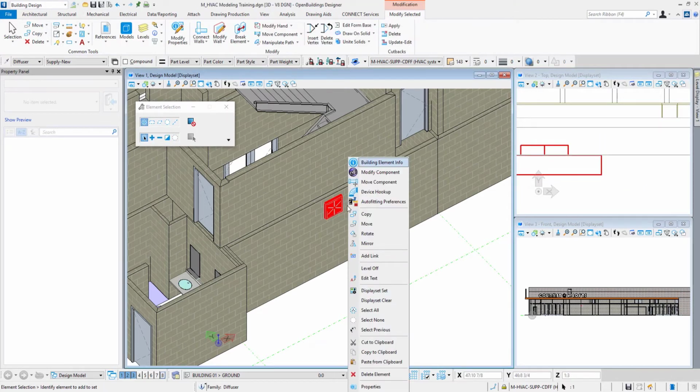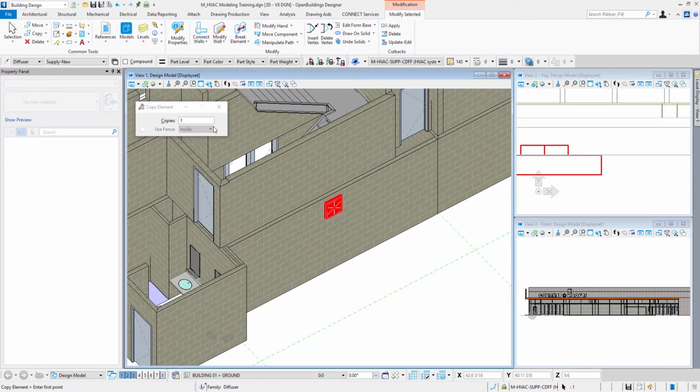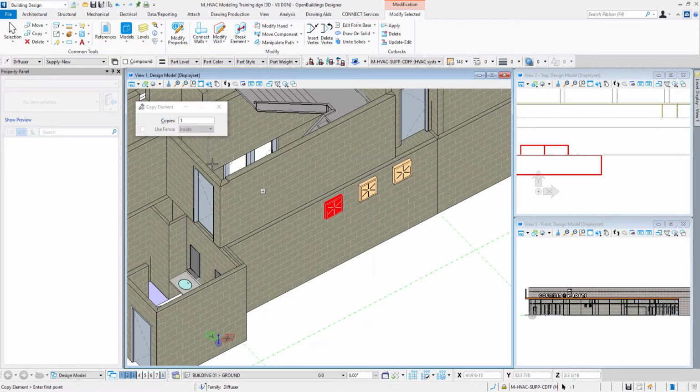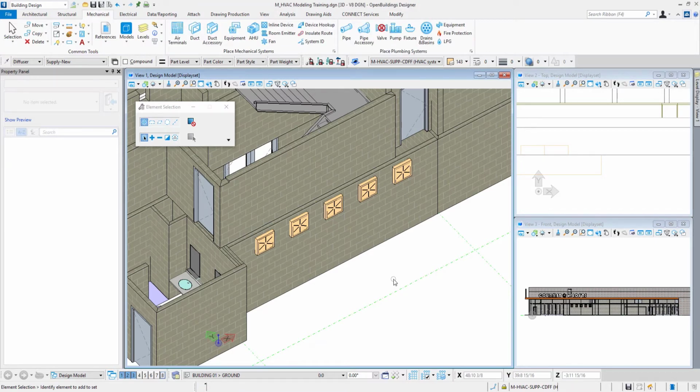Once again, if I want to copy these, let's say I make 2 copies in each direction. I'll just pick a point. Again, AccuDraw, enter to lock the axis. I'll go 4 feet in this direction. And then again, copy. I'll make 2 copies, setting that in my tool settings. Using AccuDraw. The next one I'll model is the multi-port plenum box. Air Terminals tool.